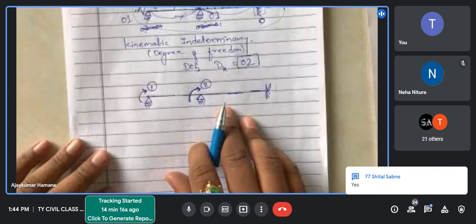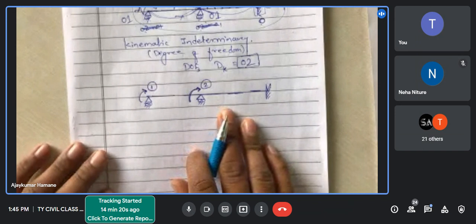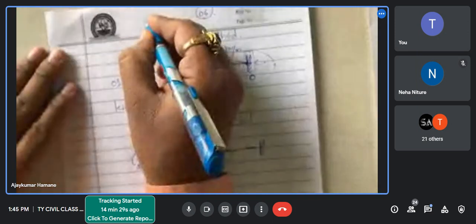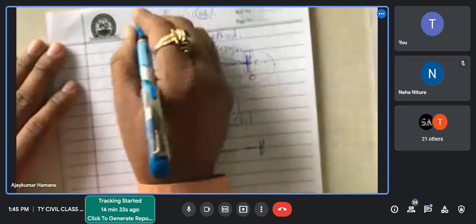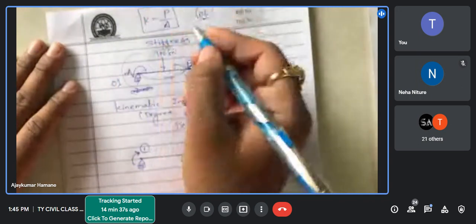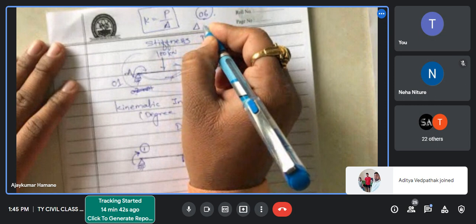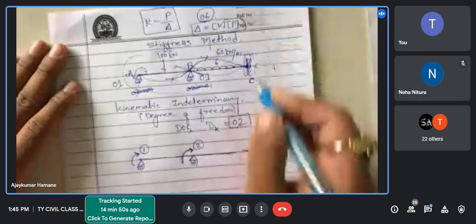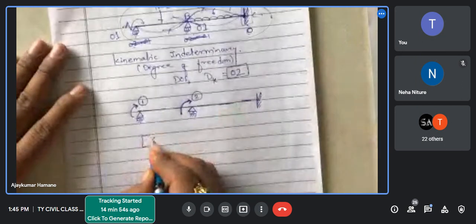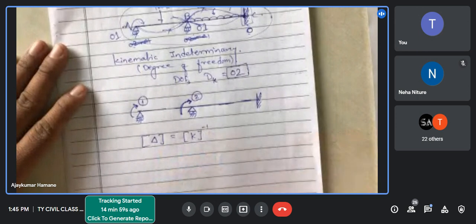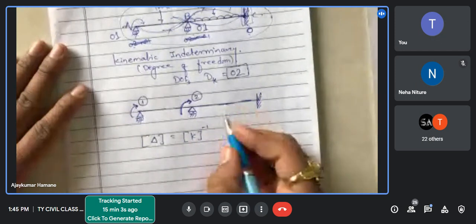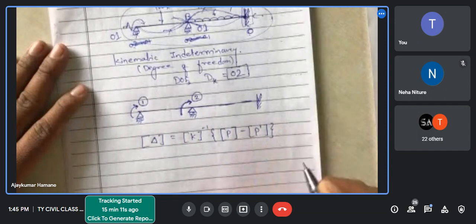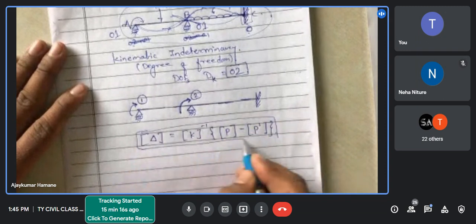After assigning the coordinates, prevent all the independent displacement components to obtain the restraint structure. What is our formula to calculate this? What is the stiffness formula? Yes, stiffness is force per unit displacement. So what we are doing? We are calculating displacement, correct? So what is K inverse into P matrix? Remember this one. So this is our formula: the displacement matrix equals K inverse into the bracket of total load minus load at the coordinate. So this is our formula to calculate the independent displacement components.